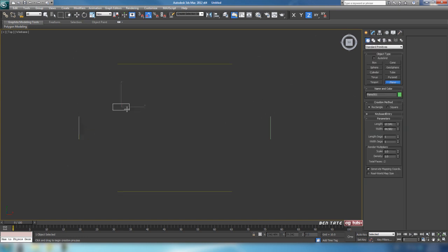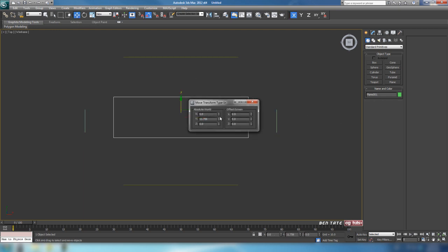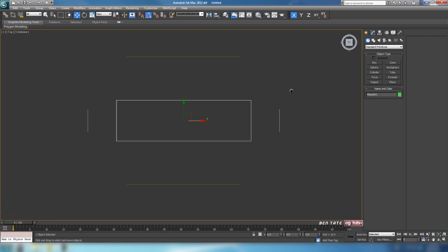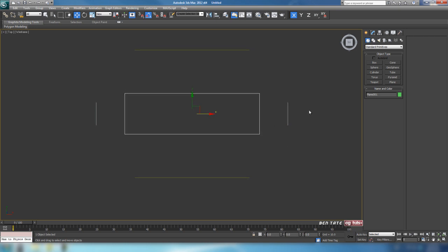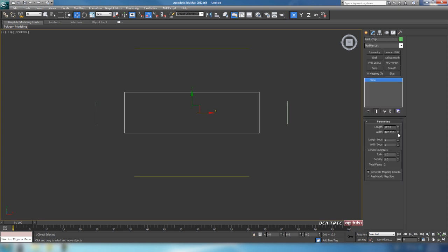And we'll just do this with another plane, so let's drag it out again in the top view and just resize it to what we need here. I'm just going to zero this out. Okay, and we'll rename this print dash top and resize our plane here. Okay, we want this one to be 366 wide and 62 on the length.